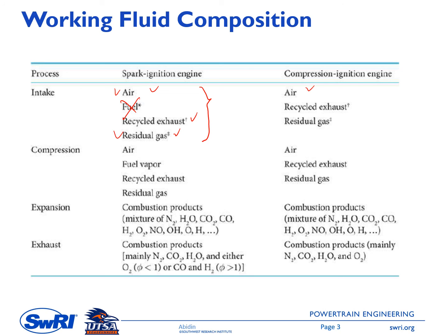We have air, and then we might have recycled exhaust, once again to improve the emission, and we have residual gas. And you can see here, we don't have fuel during the intake stroke inside the diesel engine. Why? Because the fuel is injected at the end of the compression stroke.